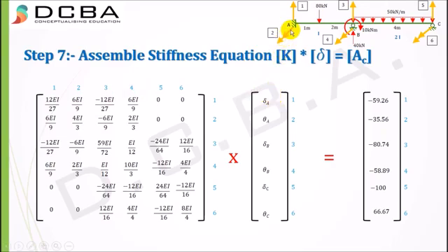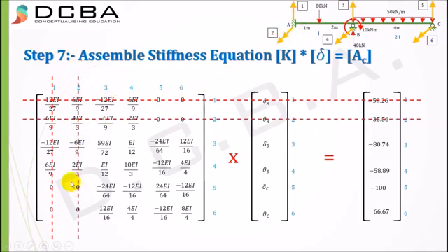As you can see, delta A, which is the deflection at joint A in the upward direction, has to be 0 because this is a fixed joint, right? And there cannot be an upward deflection at a fixed joint. Therefore, this whole thing goes, row 1 and column 1. Because delta A cannot occur, we need to cancel it out. Row 1 column 1. Again, theta A cannot occur because there is no rotation at a fixed joint. My A is fixed and there is no rotation at a fixed joint. Therefore, again, row 2 column 2.